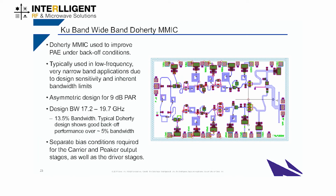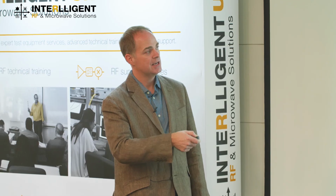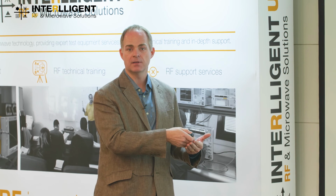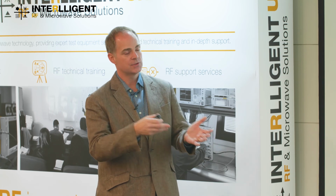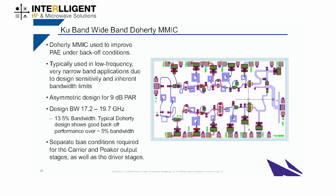Also, one of the advantages of doing a MMIC is this is actually a 3-stage Doherty with all 3 stages in both the peaker and the carrier amplifiers within the Doherty. So the input splitter is before the first stage, and the output. We actually did multiple versions of this with different numbers of stages within the Doherty, and it's basically a trade-off of efficiency and linearity versus achievable bandwidth and sensitivity. So this form actually gives you the best efficiency and better linearity. If you really need very wide bandwidth and low sensitivity for, say, manufacturability, you could do the first 2 stages as a driver, and then the output stage would be a Doherty.